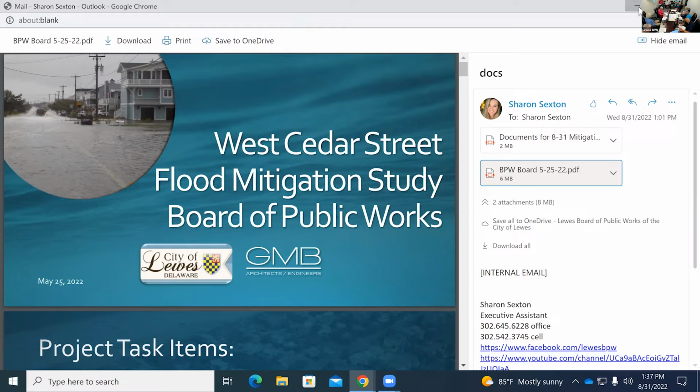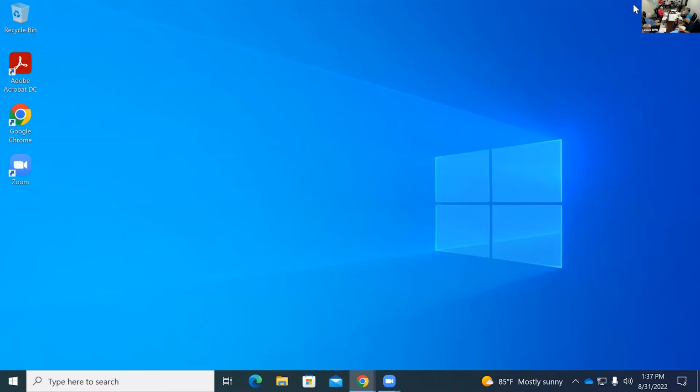On the wind load, I would advise utilizing whatever building code is current. Which is now, what, did you say 120? It should be 120, on what the city has adopted now. I think the new one, maybe in 2021, went to 130, but I'm not sure.